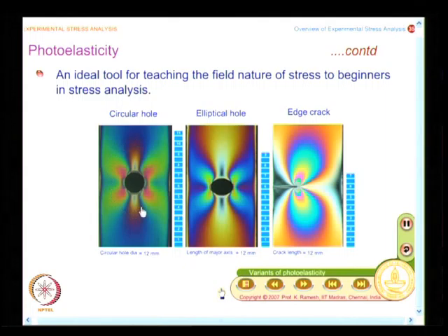So, people understood there is something, stress concentration, which you cannot neglect. And really when you look at it, what you find here is I have a uniform stress field if I do not have a hole. The moment I have a hole, the stress field becomes biaxial. The stress magnitudes are very high in this zone and also in this zone. This is one thing. Stress concentration means stress magnitudes increase, that is one thing. Not just that, even the stress field essentially changes.